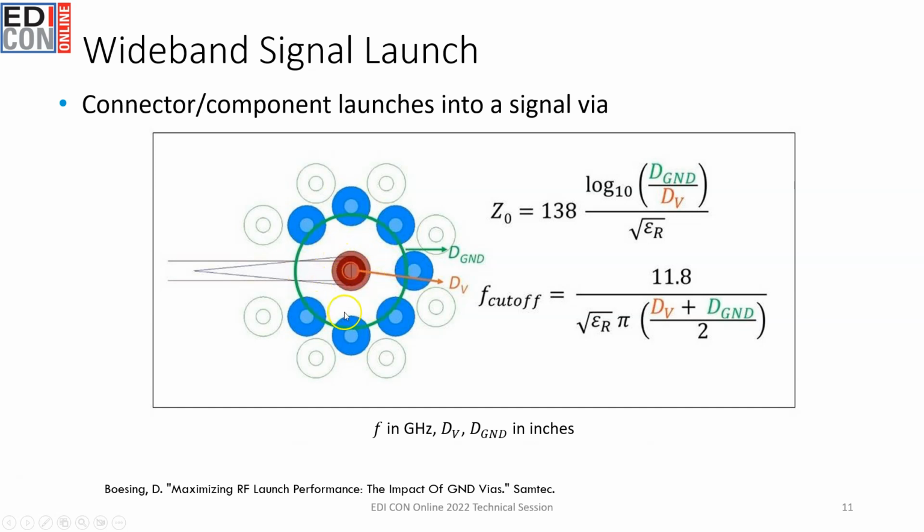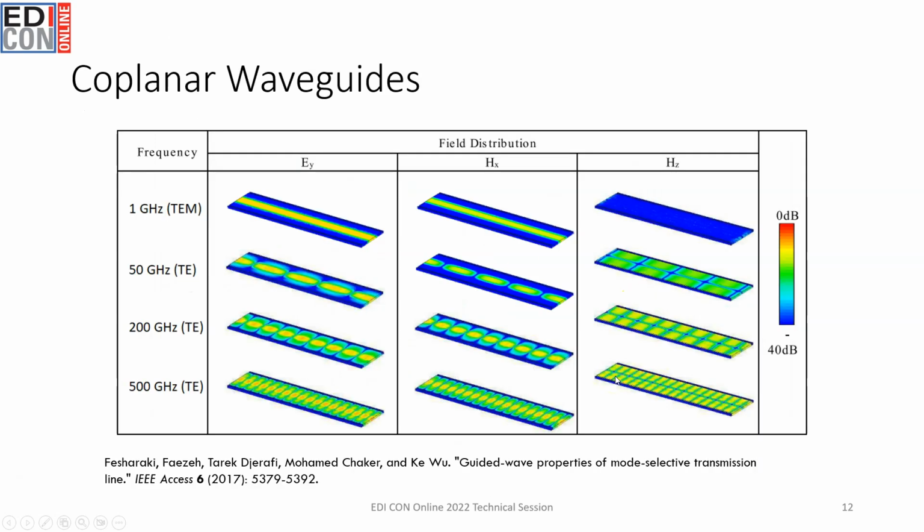So we've seen these same types of signal launches that would normally be used for connectors also being used appropriately for transceivers, specifically transceivers that use a BGA footprint. So you essentially have the pad here connected to the BGA. This is typically a blind via going into the internal layer, and then it goes off towards the antenna elements.